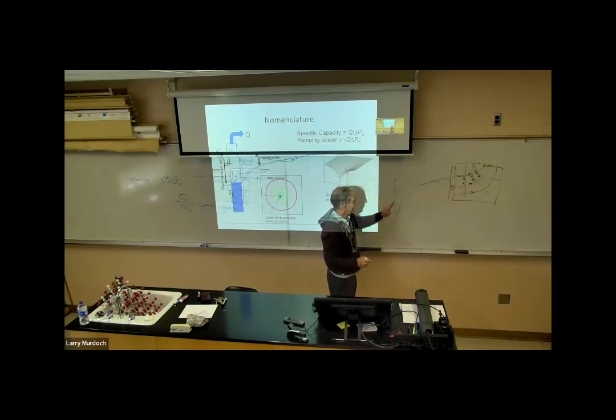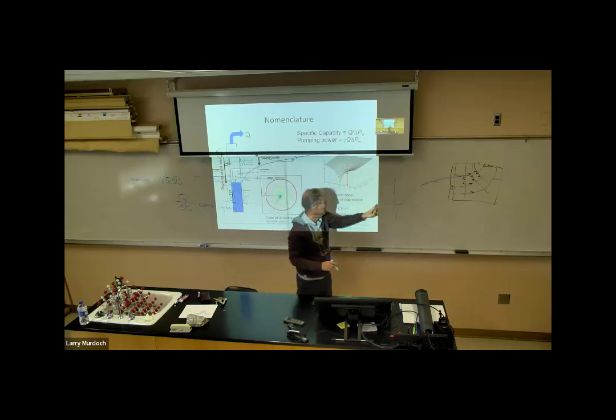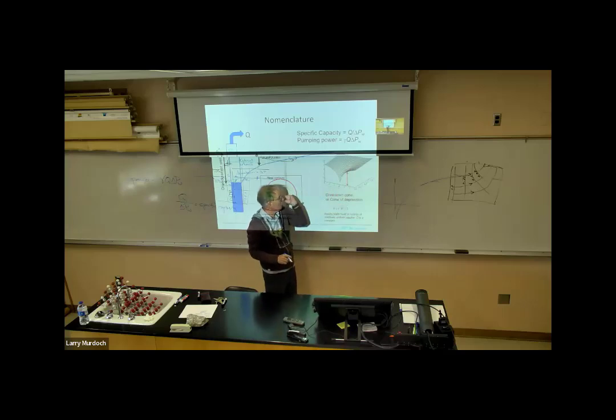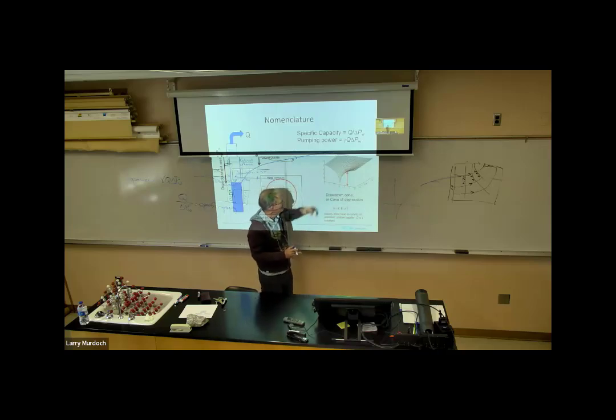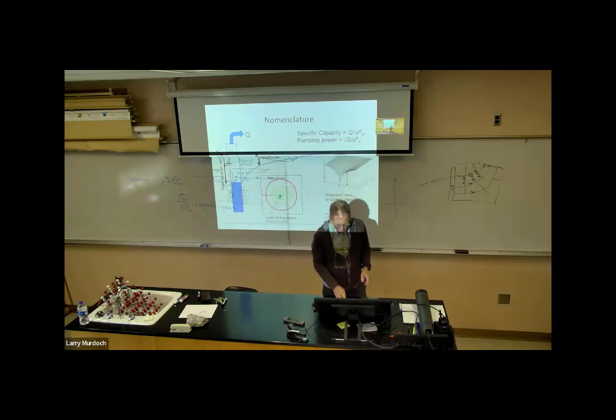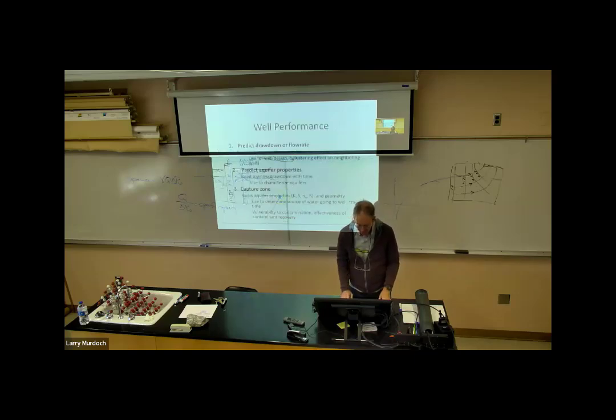So that is the function that describes the hydraulic head in the vicinity of a well. So take that and revolve it around. Here is a plot of what that looks like. That's the log function, and we just revolve it around. Okay, so that's a basic look at what the cone of depression should look like.